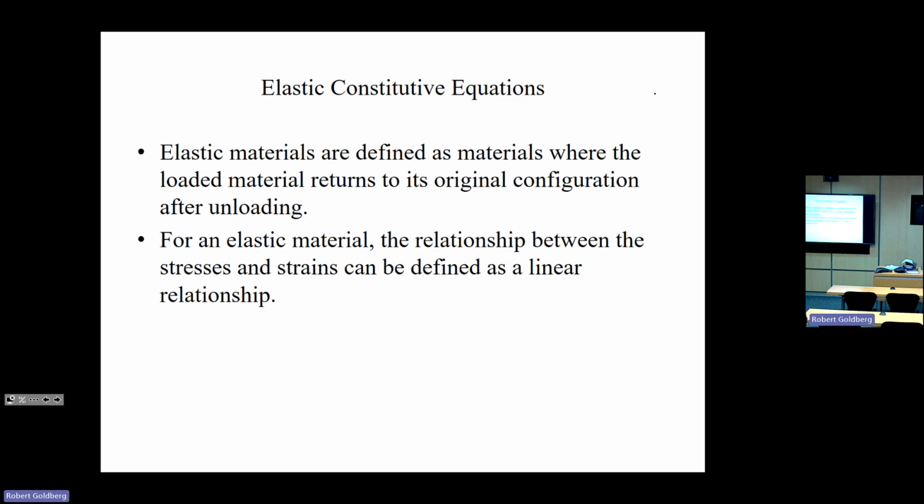Now note that for materials with plasticity, on the other hand, think of if you take a paper clip and bend it more than just a little bit, it changes its size and shape, and it has some permanent deformation. In fracture mechanics, we'll start off with assuming everything's linear elastic, but then we'll build up slowly. The first thing we'll do is say, okay, right around the crack tip, the stresses are high enough that we can have some plastic strains.